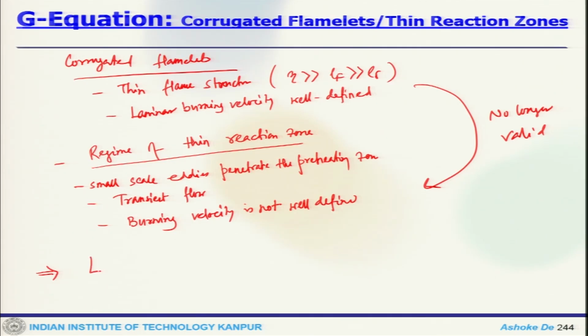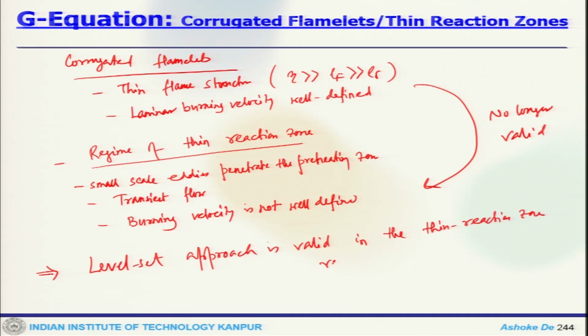So the problem that one encounters: does that mean this level set approach is valid in the thin reaction zone regime? So that is a bigger question to now answer.